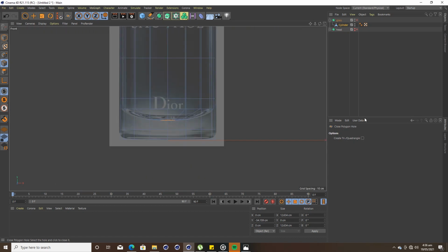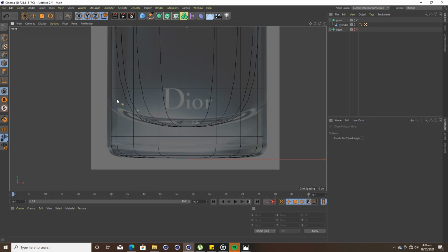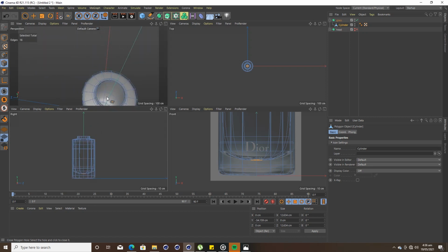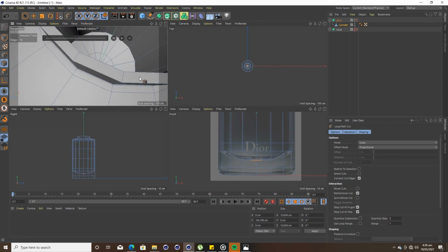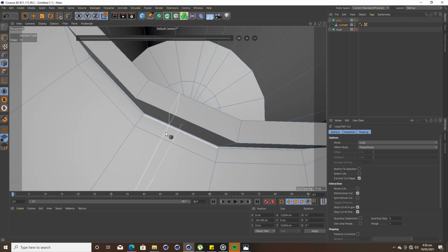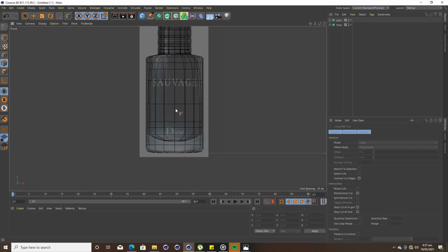But we need to make sure we add a couple of edge loops inside to make that a little smoother because it's really looking weird now. So I'll just navigate into my model again and add a couple of edge loops, right clicking and selecting the edge loop tool or just pressing U and pressing L on the keyboard to do that. Let me just delete that and recreate it. It's always very difficult to navigate inside an object. Okay, so that is that.